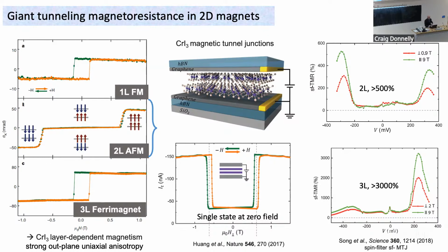So very beautiful. And what they showed was that if they measured the conductance through these insulating layers, as shown here from top to bottom using graphene electrodes, then they saw that in zero magnetic field, the tunneling conductance is quite small. And in large magnetic fields, when the moments are oriented parallel, then the tunneling conductance, the current, is increased significantly by several 100%. So this is very, very interesting.